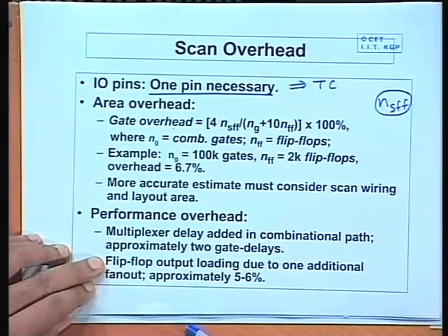So, when you increase the fan out of a gate in MOS technology, the capacitive load of the output increases. So, instead of 1, you are now driving 2 gates, so the capacitive load becomes double. So, the charging discharging time of the output node becomes approximately double and the gate becomes slower. So, in that sense the speed of the circuit drops down.